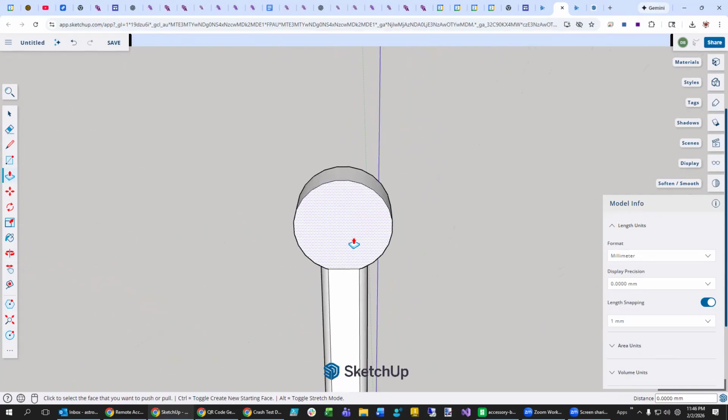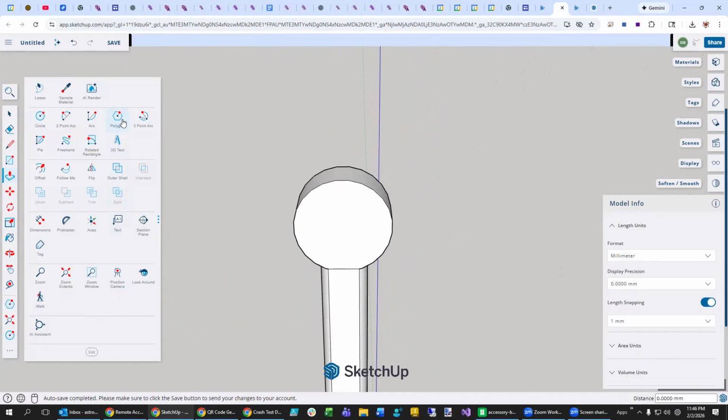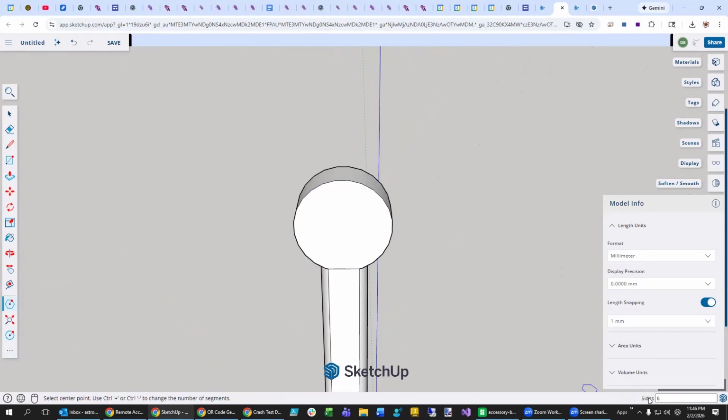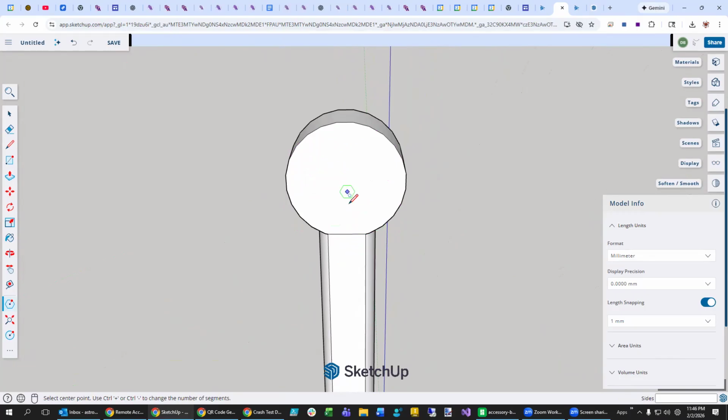The next thing we want to do is draw that hexagon on the surface. And that's probably going to be under here. And the default, as you can see down here on the lower right-hand side, is 6 sides. So we try to find the midpoint of that somehow. I don't know if it's going to let us just find it. Do we click on the outside? It almost highlights right there. Okay, it looks like it did it. And I like to have it maybe about this size here with the flat part going outward. Let's see if we can do that. Now, if we don't like this, we can always hit Control Z later on and undo this later.